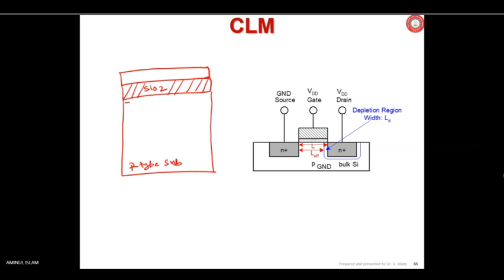In this region we have many free electrons, which is called the inversion layer. This region is inverted. Basically, it is P-type, lightly doped, and the concentration of electrons here depends on the positive charges deposited here by connecting a potential V1, right?